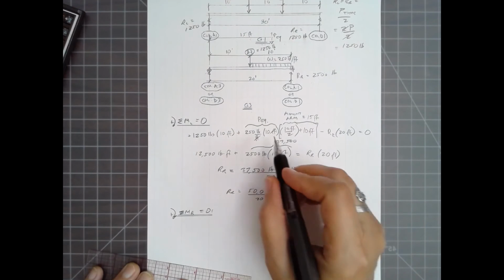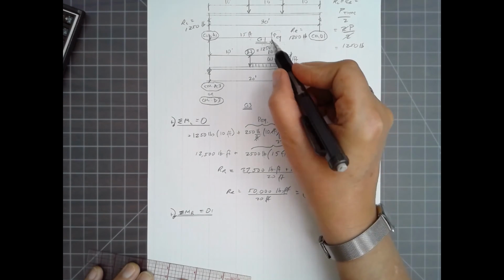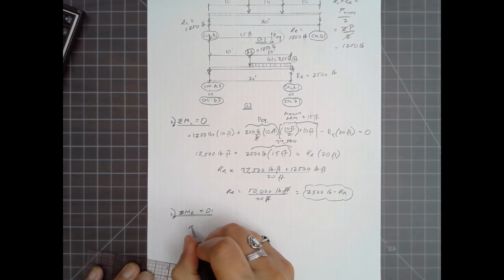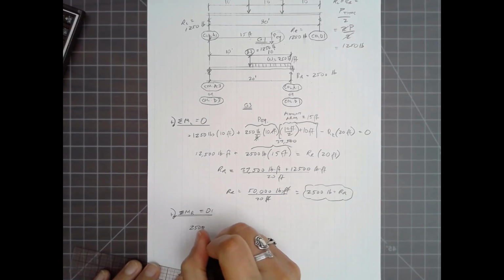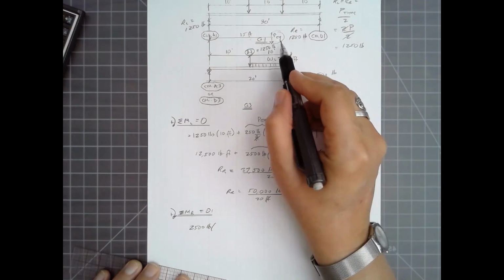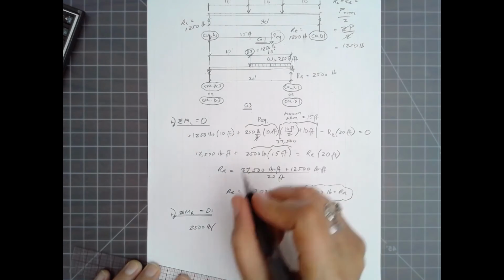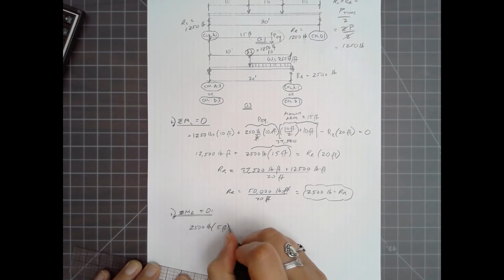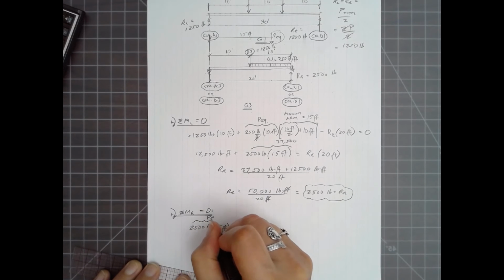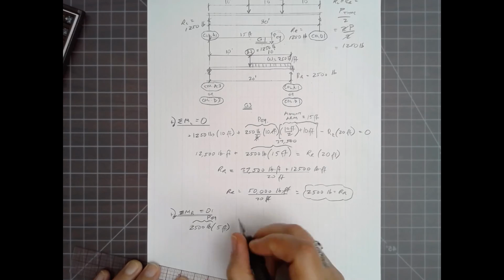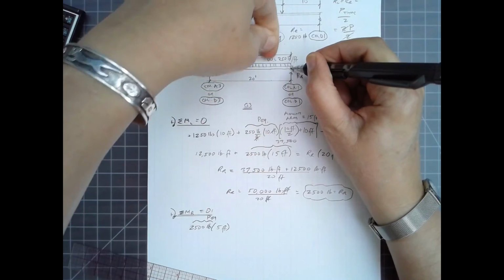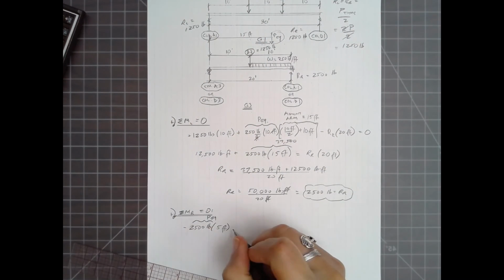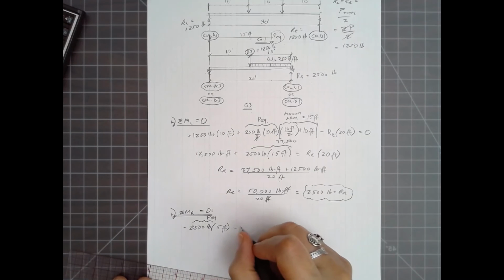So I'm just going to take my P equivalent here, since I've already computed that. Now its moment arm is only to the center here from the end, so it's 5 feet. So again, this is the equivalent P. If I'm calling clockwise positive relative to this point, now my force is rotating counterclockwise, so this has to be negative, minus my middle load, B2, 1,250 pounds.